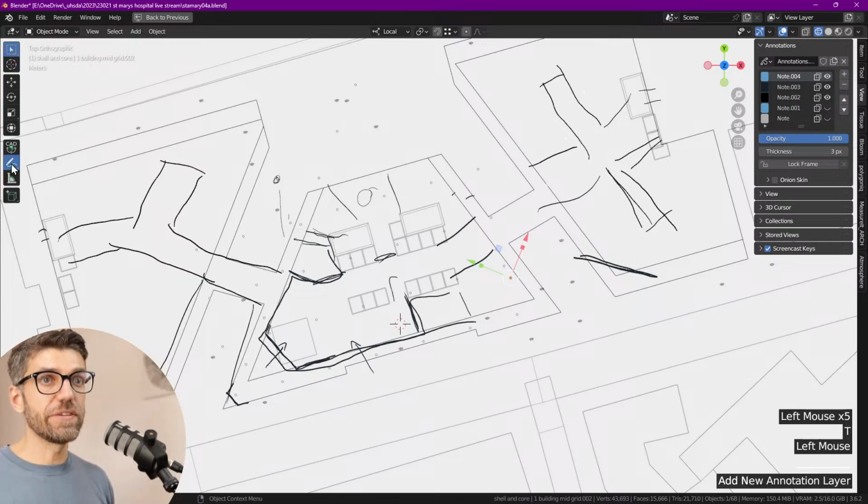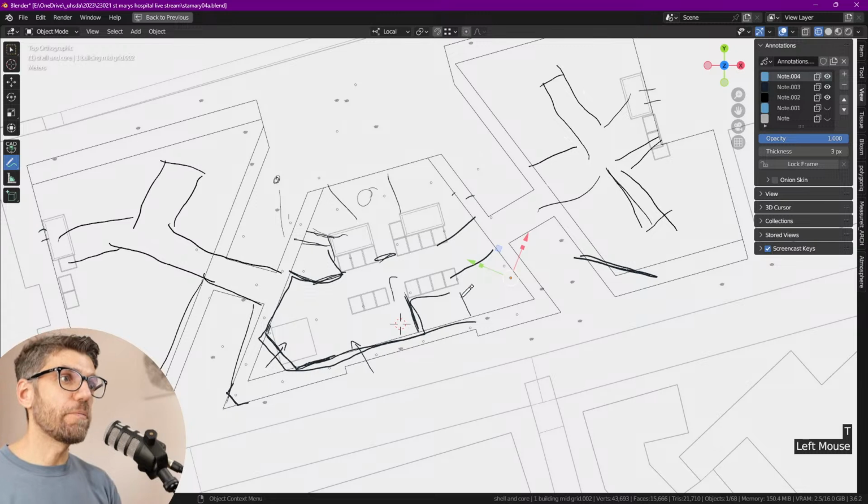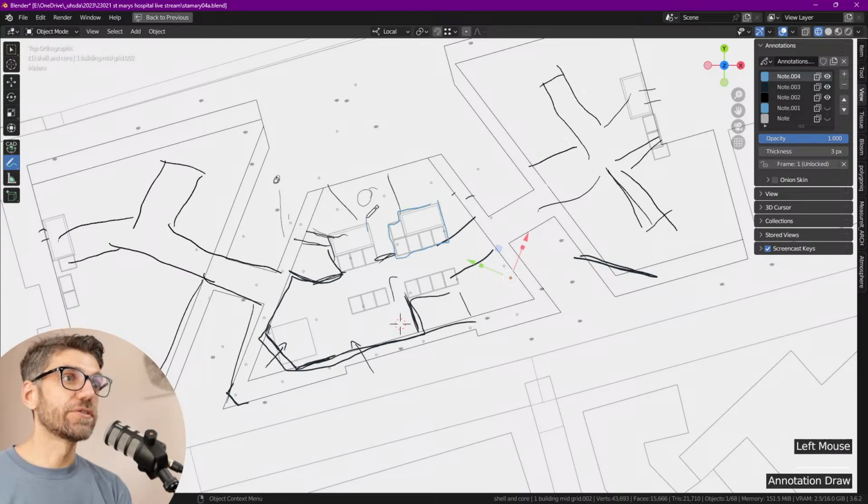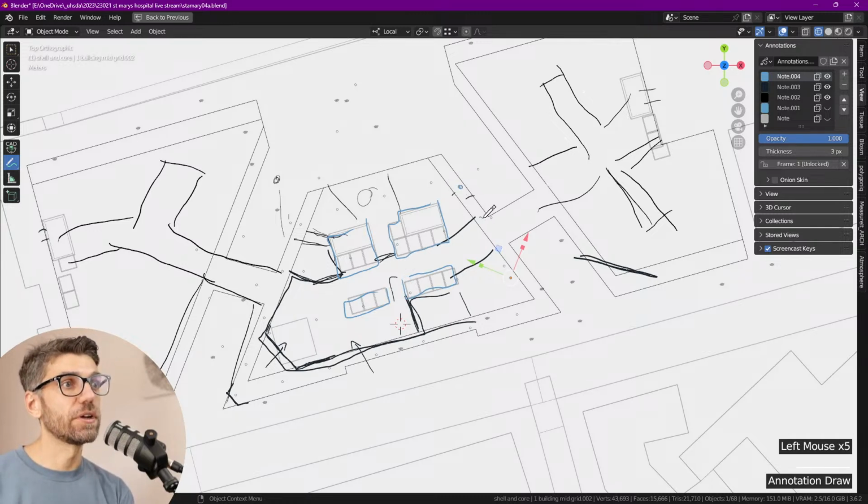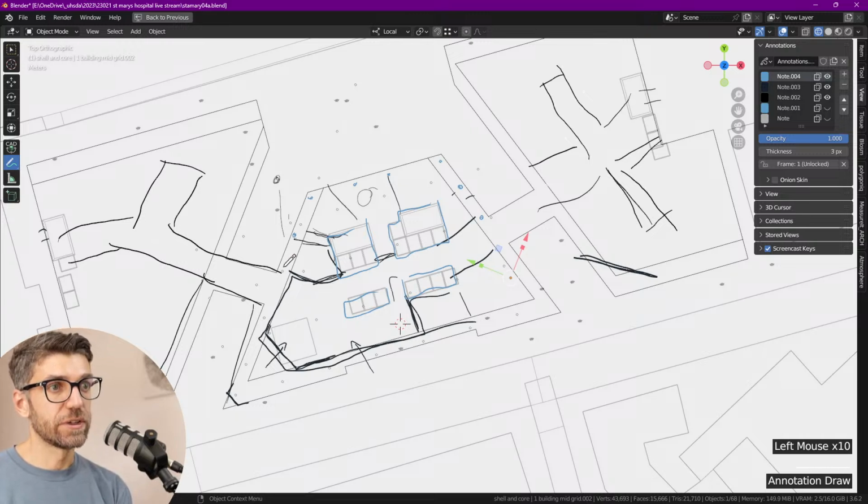Because we have this kind of short span generally, this core, like the structure around that core, is going to be enough to support a lot of our building. So we don't need columns anywhere close to it. So from that core on, we probably only need a column here, a column there, and so on, a column in each of these positions.